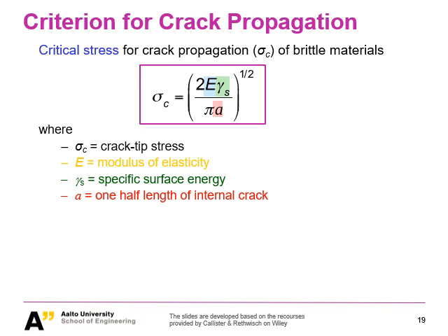And what I can tell you is the derivation is knowledge from several generations, and it's very beautiful. And here I'm telling you the critical stress for a material to trigger the crack propagation of brittle fracture is given in such an equation. So sigma C is the so-called critical stress.